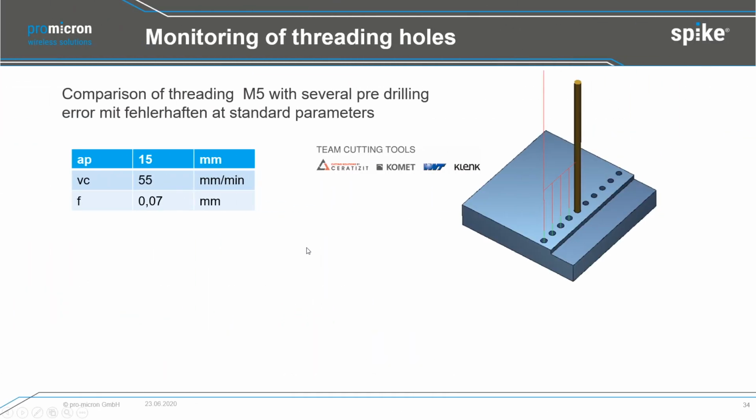So that's why we have set up a trial with 10 pre-drilled holes, some of them good and some of them bad, and then we put in the tapping operations. And we were lucky in the last video which we have done, the tap did not break, but the process before which we had done, we exactly caused that problem. The tap broke because of a bad pre-drill tolerance.